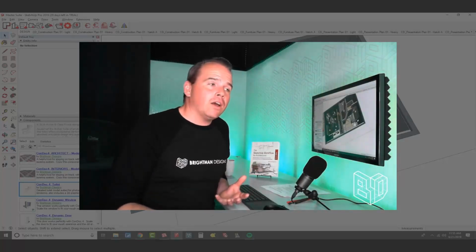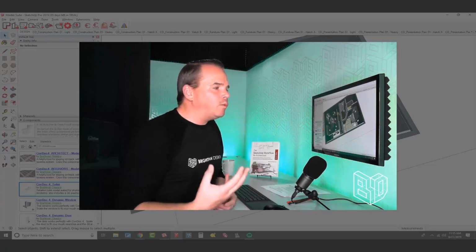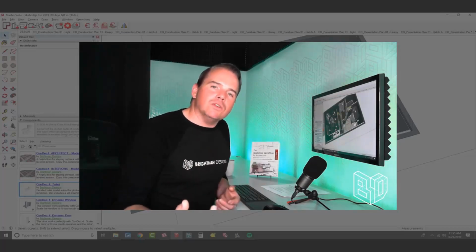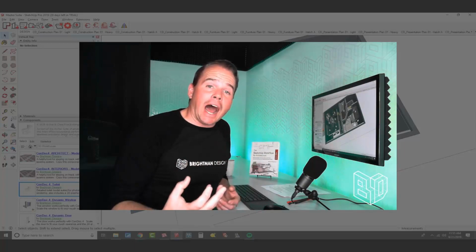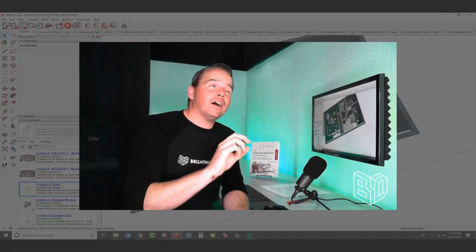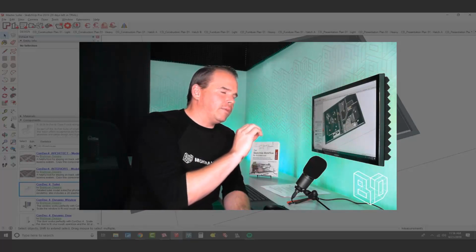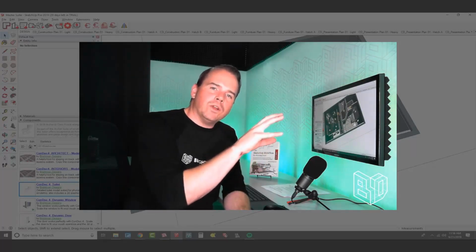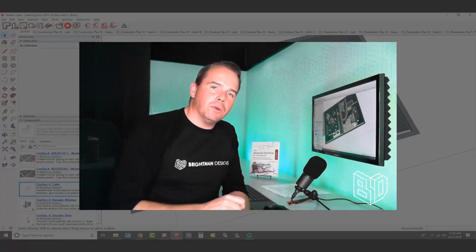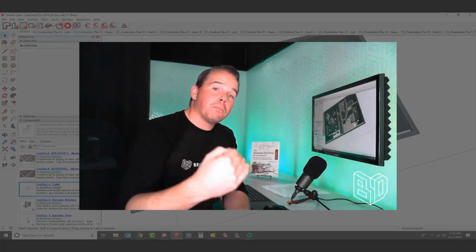And if you're working with ConDoc, we stack viewports to give you several line weights, all right? So think of it like this. Line weights in SketchUp and layout are a product of the multipliers that you set up in the SketchUp style. A style has two critical multipliers: a profile and a section cut. When you set those numbers to 2 and 3, they get multiplied by the line weight that you assign to the viewport in layout. That's what creates roughly 3 line weights per viewport.